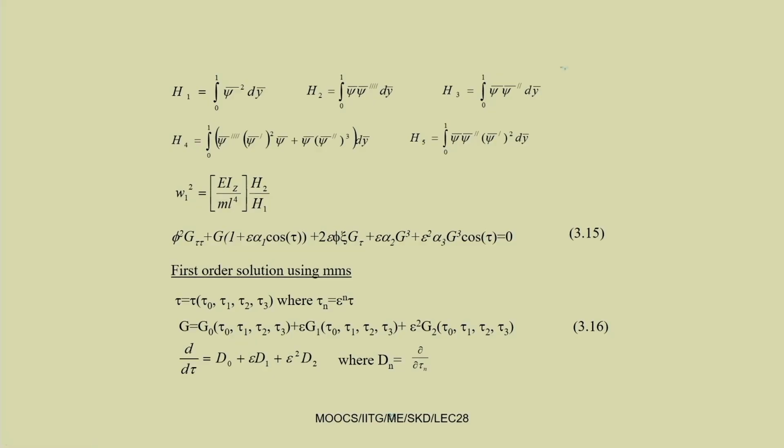As you are taking a continuous system, the derived equation of motion is in the form of partial derivatives, so the state variable is a function of both space and time. You can reduce it to its temporal form, that is to its time form, by applying the generalized Galerkin's method.